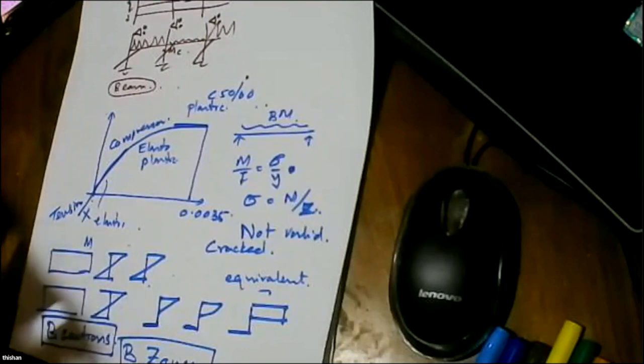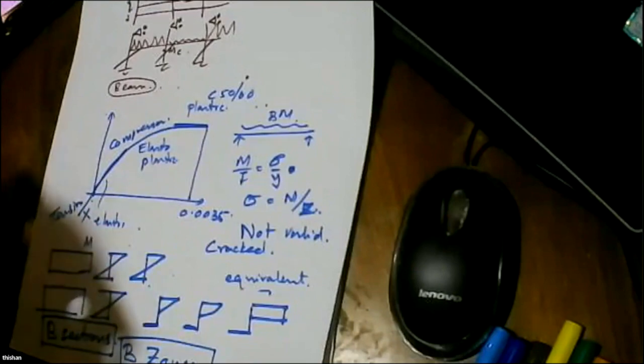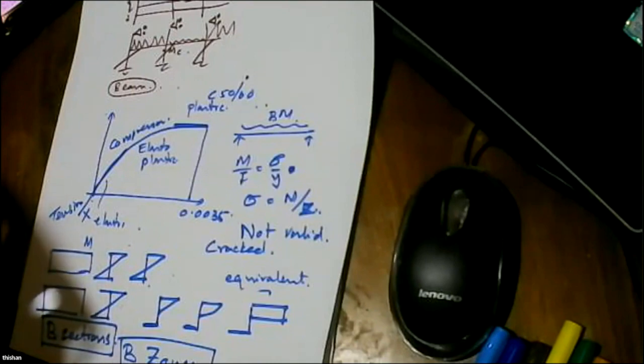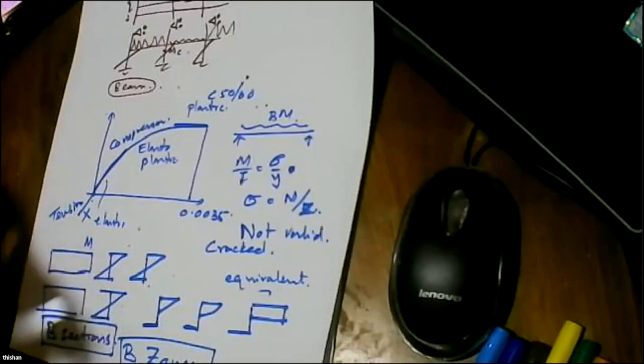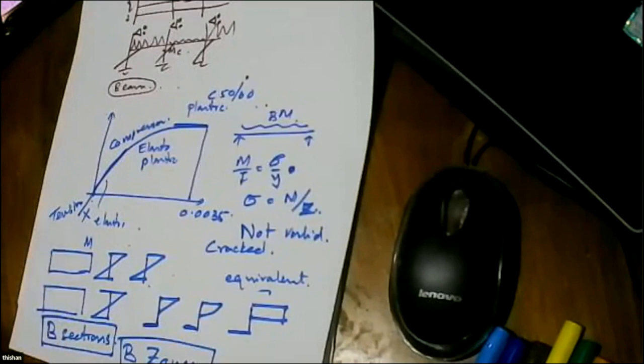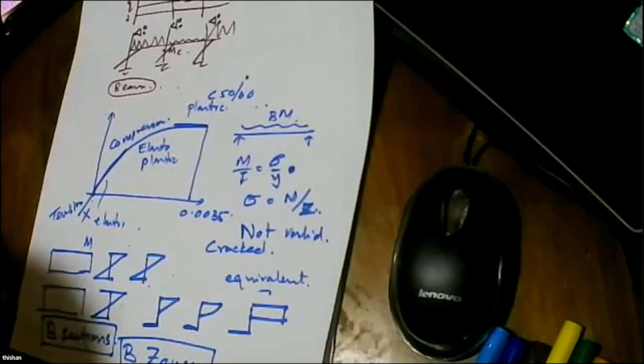So we solved the problem that way, and we reduced the number of piles by 50%, because now our piles will be carrying much more. A 1200 pile can go up to 12,000 kilonewtons, and a 1500 pile can go up to 17,000 kilonewtons. Then to allow for that, we have to ensure that the pile has shaft capacity. For the shaft capacity, we said, okay, instead of using 30 megapascal cube strength concrete, let's use 40 megapascal cube strength concrete.